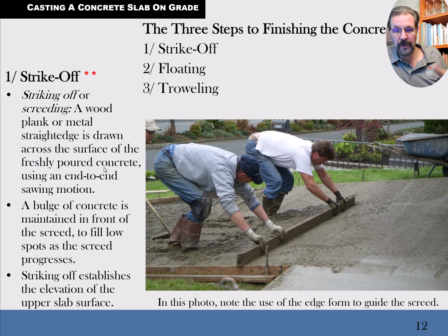There's always excess water in the mix that you don't need, except maybe for placing, especially if you don't have any additives in it. The excess water that you add to concrete will weaken the concrete, but you do need a certain amount of flowability and workability in the concrete in order to get it placed, especially in a slab. Whereas in a wall form, you can have a stiffer concrete mix with less water in it. And of course, I've talked in the concrete technology section about how we can use additives that make the concrete behave as if it's got extra water in it. But in truth, behavior and actual water are 2 different things.